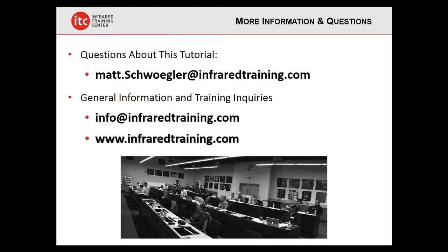So one of them that came in early on was, can we interpret temperature below atmospheric temperature? Which I'm not totally sure. I think that's what they meant to say. Yeah. So can we see things that are below ambient? Oh, absolutely. Yes. The infrared cameras today can not only look at very high temperature objects, but we can look at very low temperature objects too. Some cameras go as much as 40 degrees Celsius below zero for their temperature measurement ranges. So yes, absolutely. And sometimes what's coldest is an indication of a problem rather than what's hottest. All depends on the system that you're looking at.